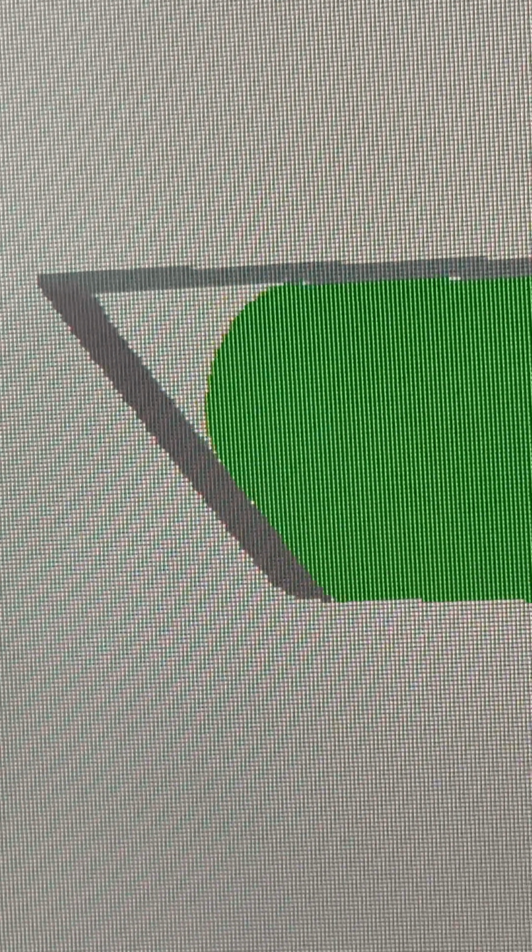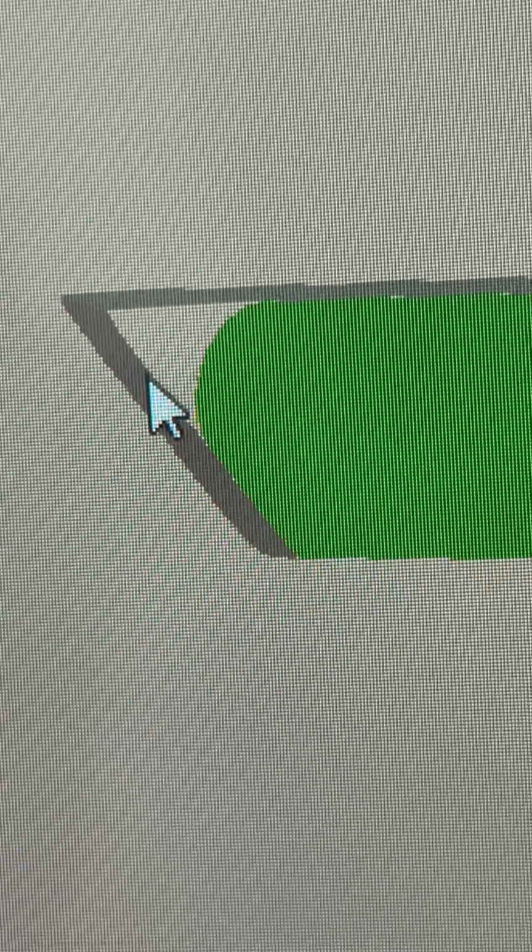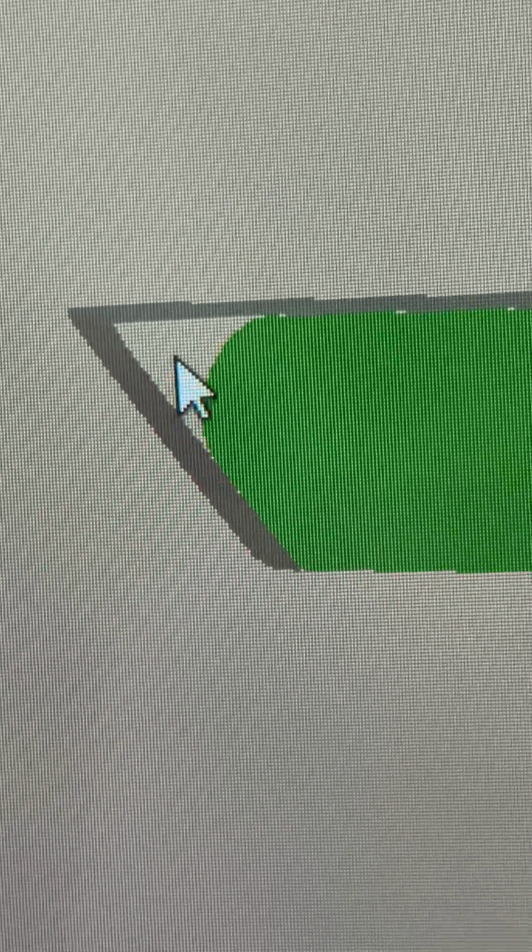Essentially a 1/16 inch end mill. The green represents the area that's actually going to be cut. You can see how much of that point gets removed, and that's a very small end mill. I could come in here with a 1/32-inch end mill, and maybe half of that material that's left, maybe about right here, would get cut, because we're going half the size.